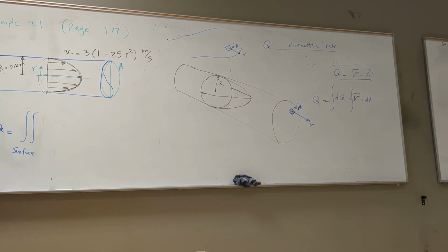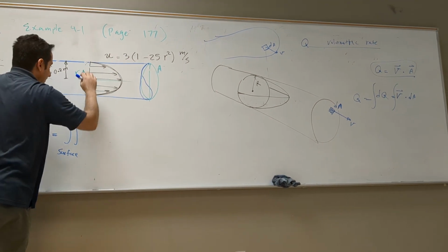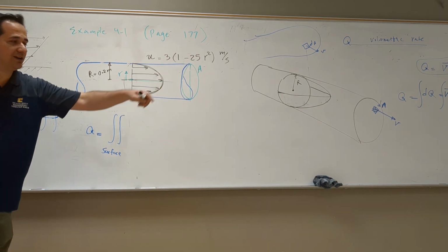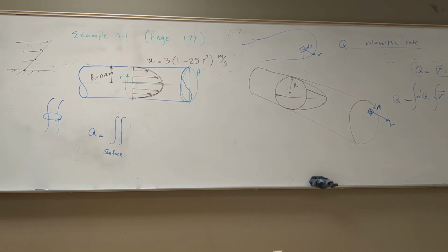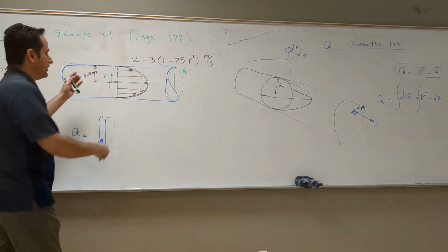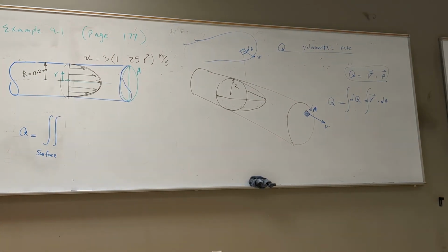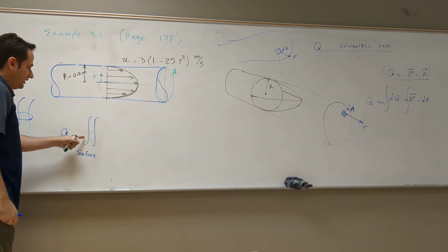That's right. When you see the ring, that means I was integrating over this, and this, and this, and this. And if I put the ring here, from the physical problem, before even doing the mathematics, what would be the result? Zero. The net mass is zero. Why? Because it's incompressible. Nothing is compressing here. Nothing is accumulating. Everything coming here is exactly whatever you need. So there is no ring here.